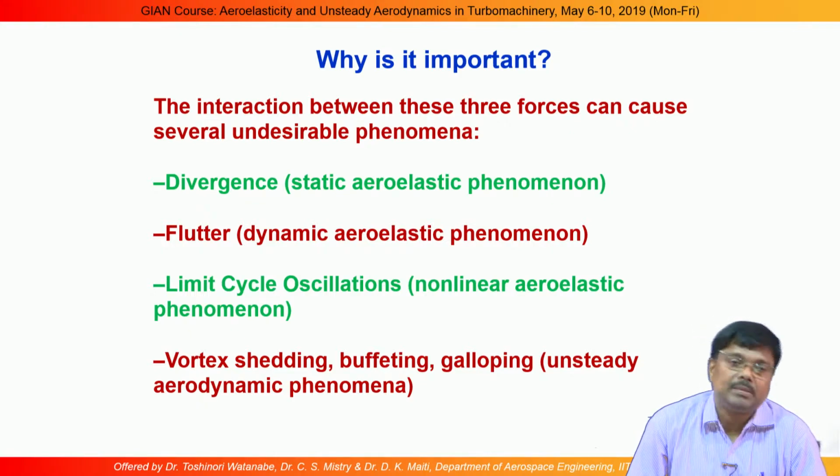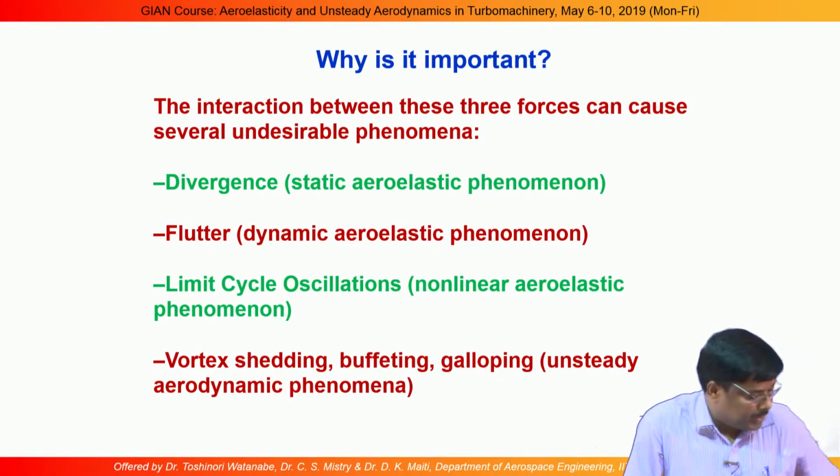So when it is flying, there may be this nonlinear aeroelastic problem, what we call limit cycle oscillation. Similar types of problems are there in flight control also, flight mechanics also. Then we have certain other things: vortex shedding, buffet, galloping. Those are all unsteady aerodynamic load phenomena.